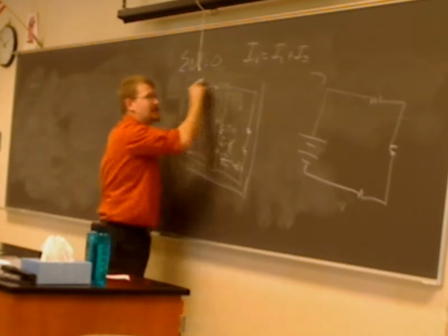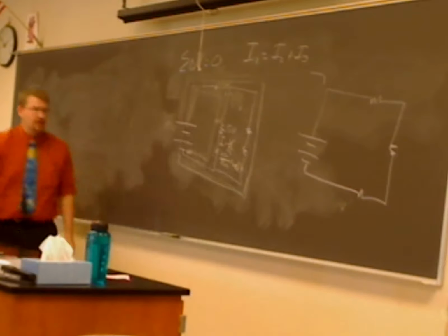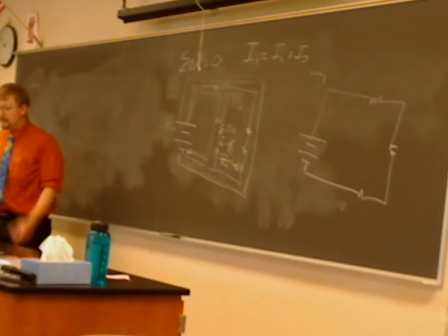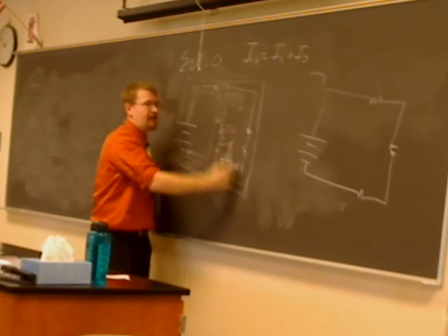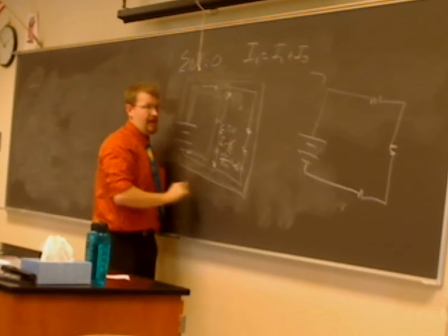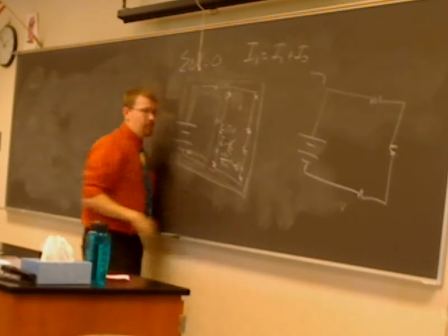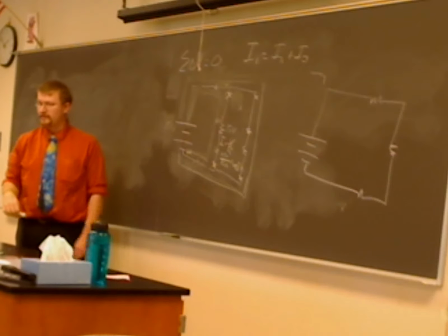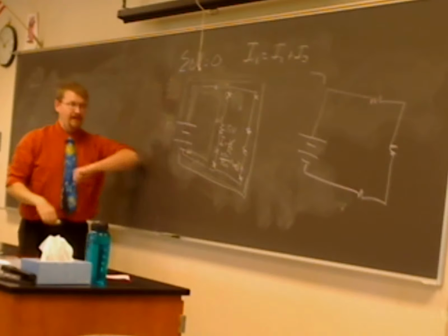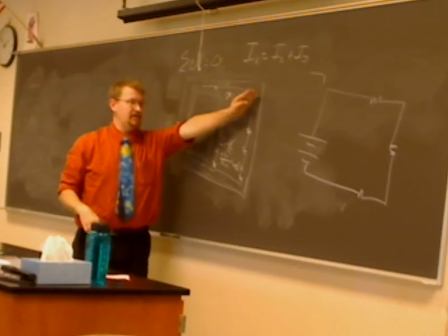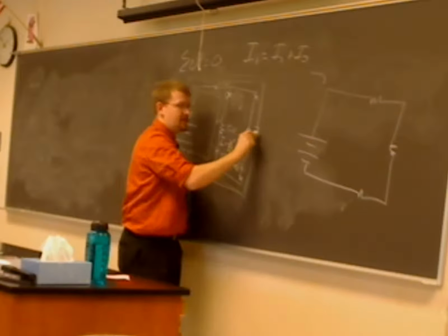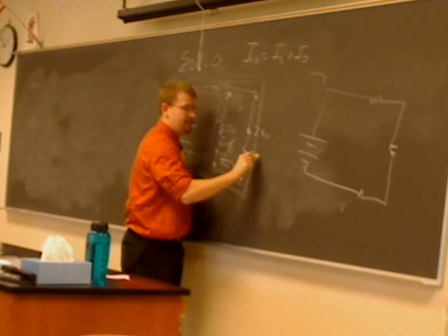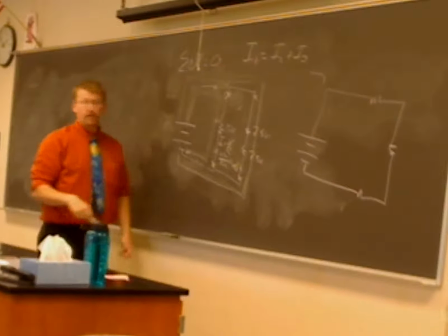There's two different quantities that we're dealing with there. So, going around the outside loop, how many volts does the charge have to lose going around the outside loop? Still 15 volts. So the key idea here is that if these two branches are in parallel, from this point to this point, both of those paths have to use up all the voltage. So on this one, we only have one thing taking the voltage away. Over here, we still have to lose 15 volts. How many things are there though? Two. Are they the same thing? Yeah, they're both 10 ohms, right? So we can then say these are both going to take away 7.5 of those volts. And then I'll just add the 15.